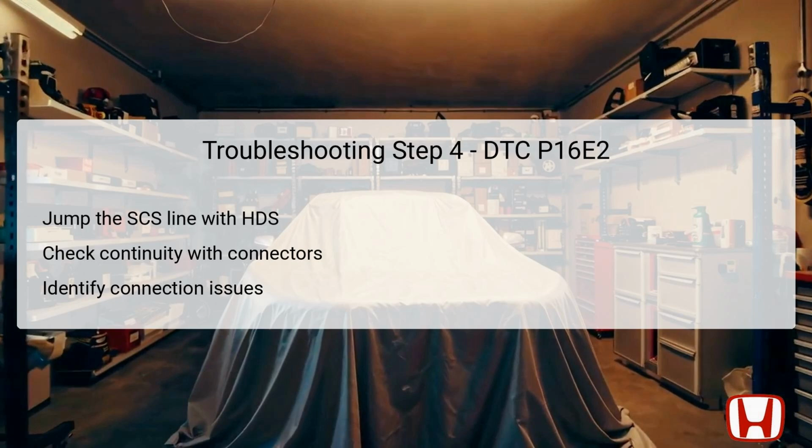LIN communication line. If continuity disappears with any connector disconnection, then the LIN wire is functioning properly. Subsequently, it would be necessary to replace the part that caused an open. If not, it indicates there's likely a short in the LIN wire that needs repairing.